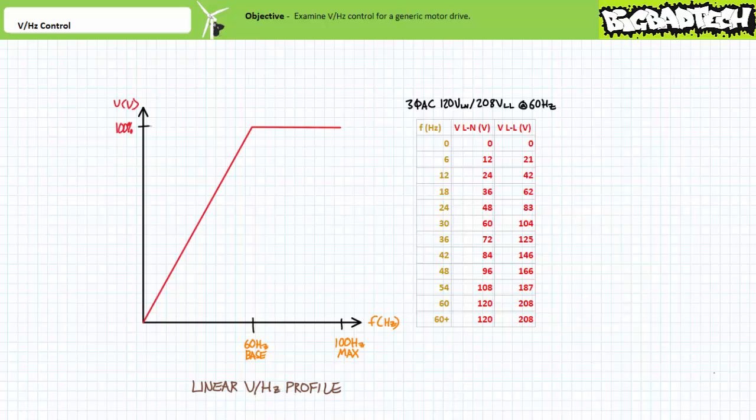The obvious solution to this problem is to vary not only excitation frequency, but also applied voltage magnitude, such as volts per hertz control. Volts per hertz control proportionally lowers applied voltage at excitation frequencies below the base frequency. At the base frequency and beyond, up to maximum, full voltage is applied. In summary, given low voltage magnitude at low frequency, the current stays low.